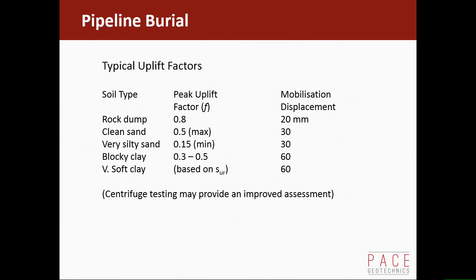So when you push it back into the trench, it remains as lumps. Because it's in lumpy material, it doesn't have an undrained shear strength, it'll tend to act as a coarse, granular sand, gravel type material, so it will be blocks. And you use an uplift factor and this sand equation, okay?